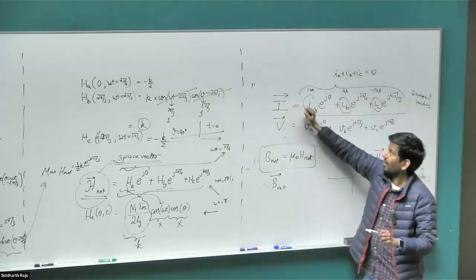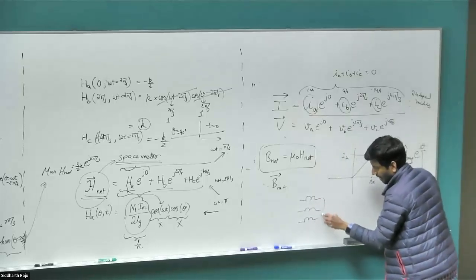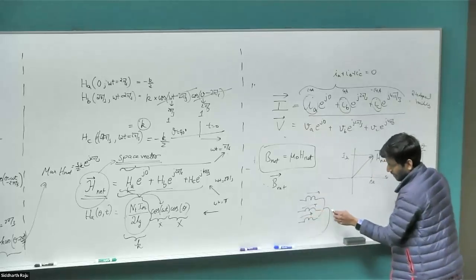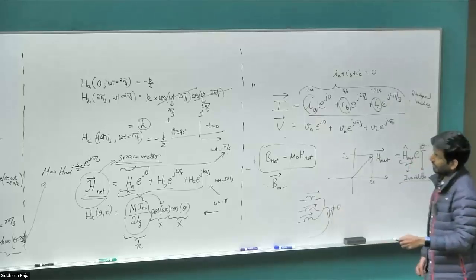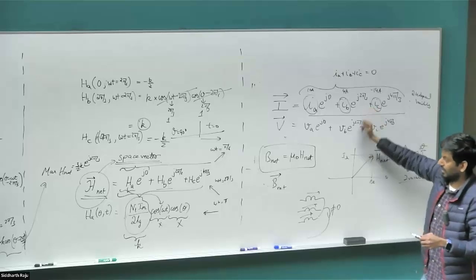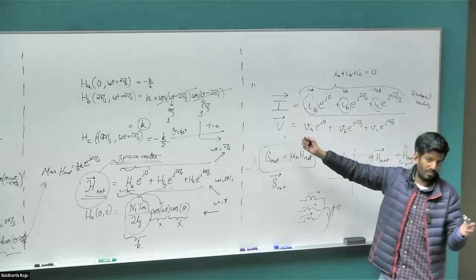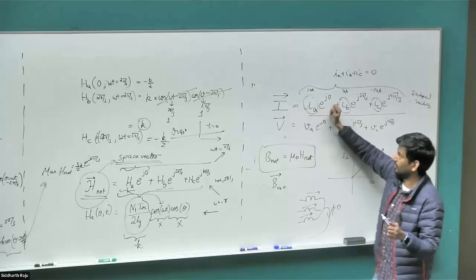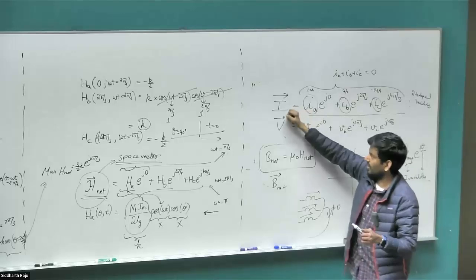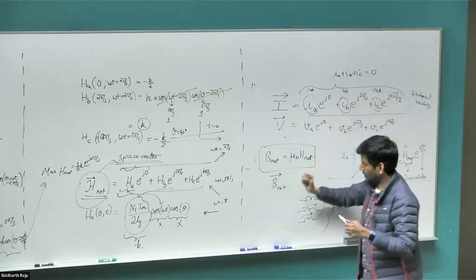Right? That's very critical. If you have a case where you have your motor windings, and then there is a neutral which you have access to, and the sum of these three currents is not 0, then this would no longer apply. Because you're having three independent variables on this side, since the sum is not 0. You're mapping it onto two variables, then you're losing some kind of information. You can't go from here back to this. But if you have this case where the sum of the three variables is 0, then you can go from here to the space vector and get back to your time domain values. Alright. So is this part clear?